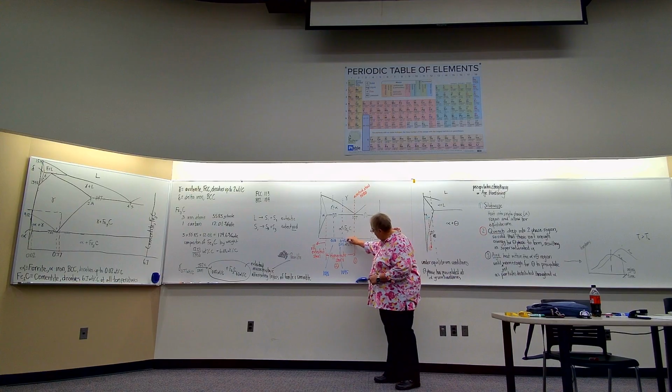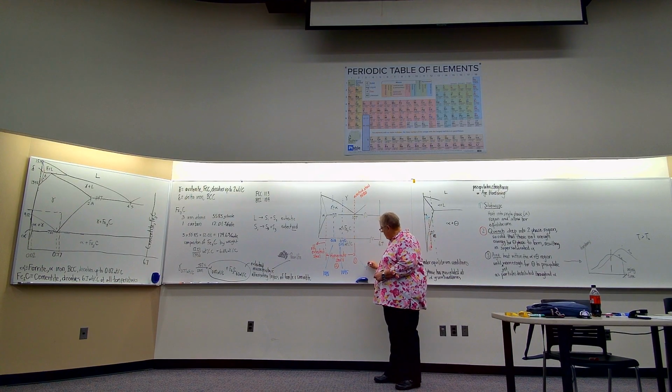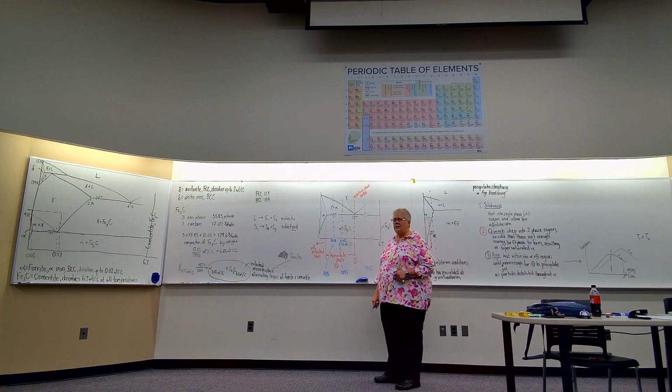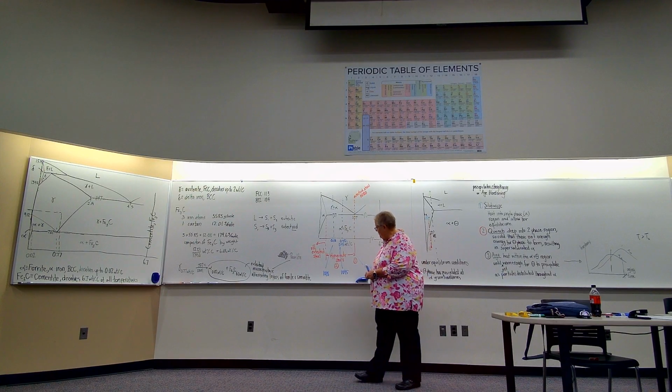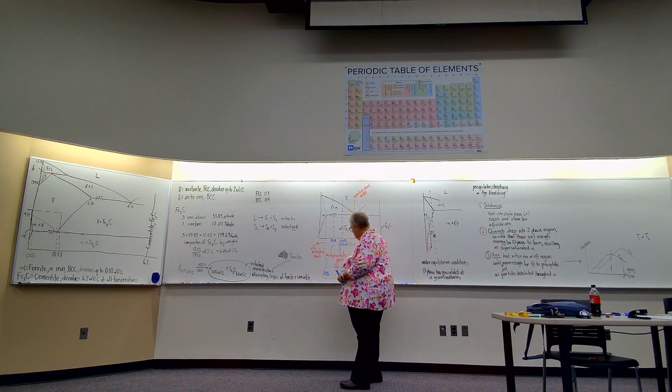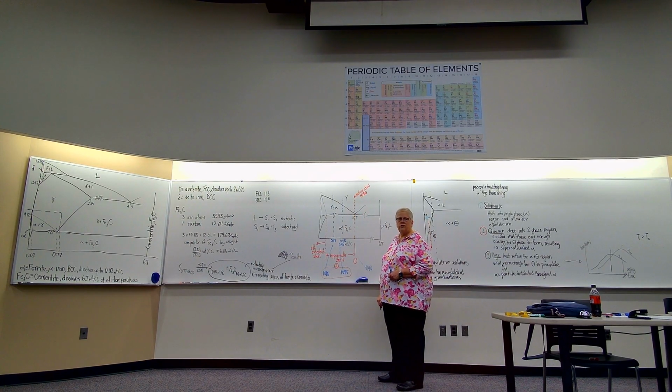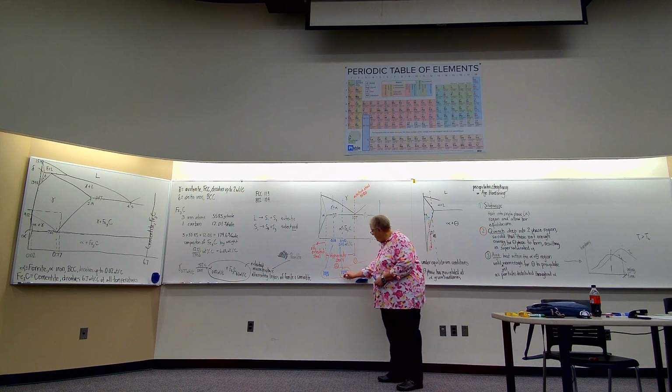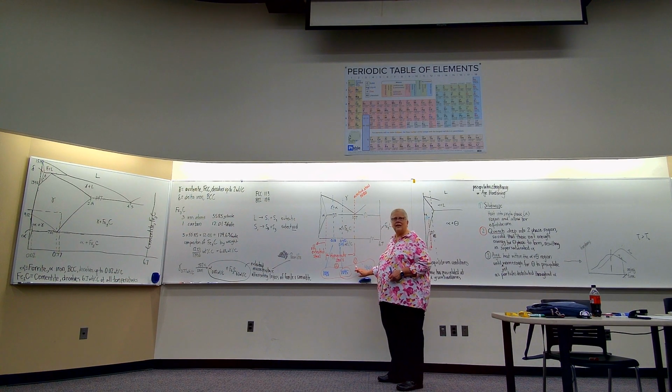And then we also have 4140 steel. That's an alloy steel. So for the lab experiment, you can see the effect of percent carbon for those two, and we can see the effect of alloying elements, because the carbon is about the same with these two.